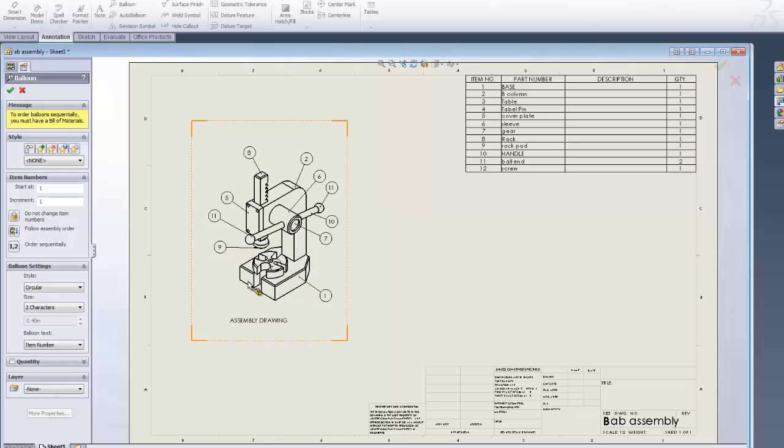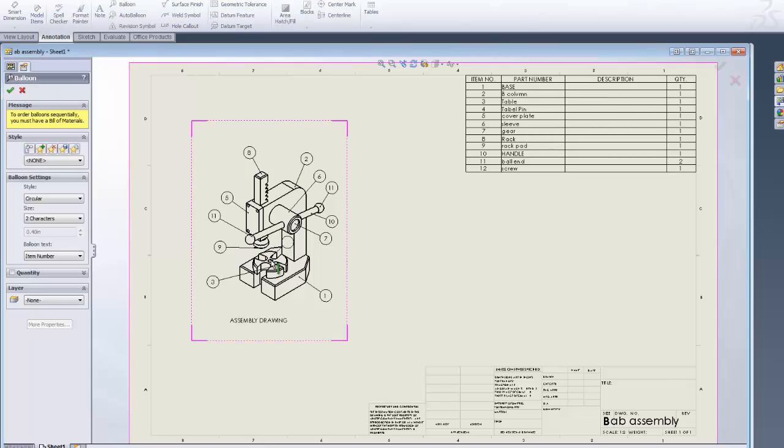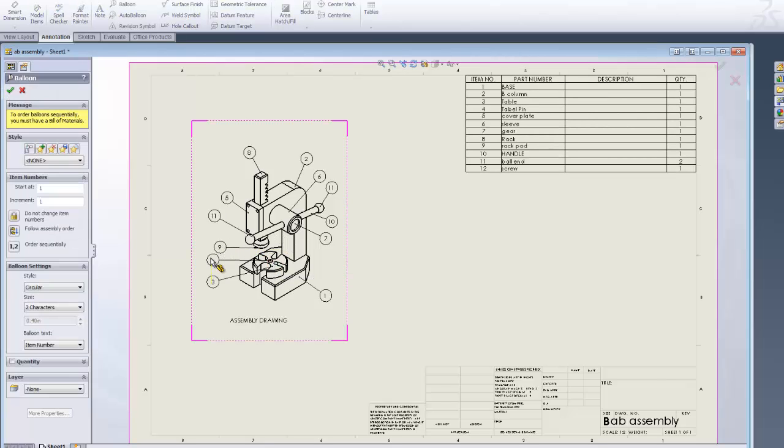As I finish out labeling each of these, again, the idea is to not have them overlap. And in that case, I got the wrong one, so let me just undo that last one there and come back in and correct that by selecting the table pin. And we have our parts labeled. From here on out, the working drawings will be composed in the order in which they show on the bill of materials. So I could go into now my next sheet, dimension the base, then the column, then the table, table pins, and so forth, as I go through my working drawing.